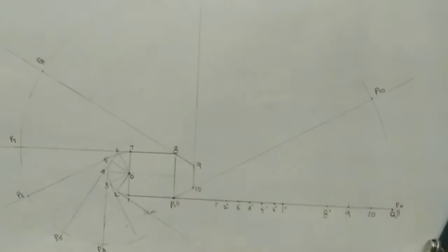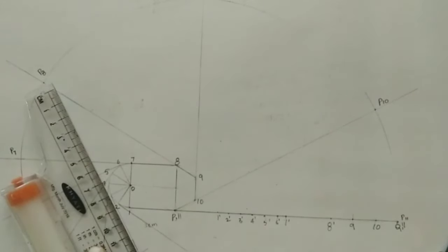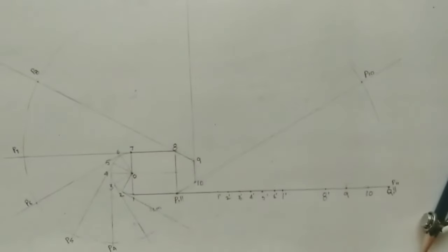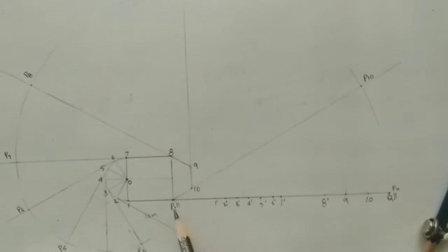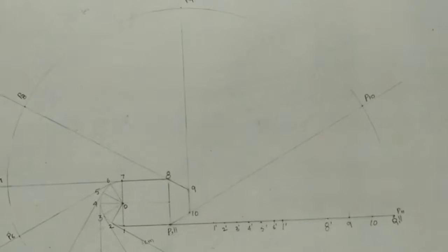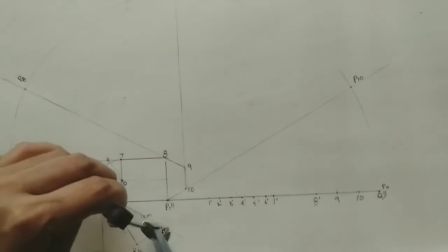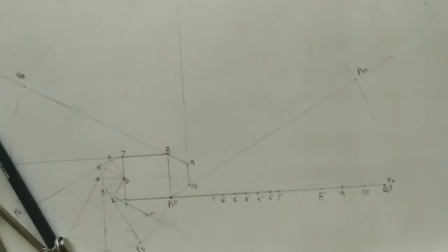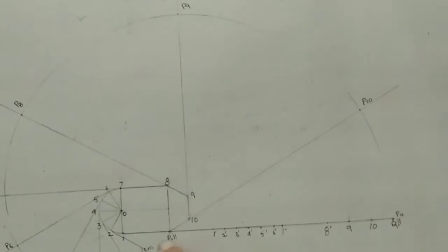So extend the line here, the tangent, so that we will get the intersection point. So I have extended the tangent. This is the P3 intersection point. After P3, mark P2. So take P2 length. Mark on the 2nd tangent. 2 as center, just do an arc here. So this is P2. Okay. After getting P2, mark P1, it is coming here only. Okay, so it is P1 also, because we did tangents at all the points.